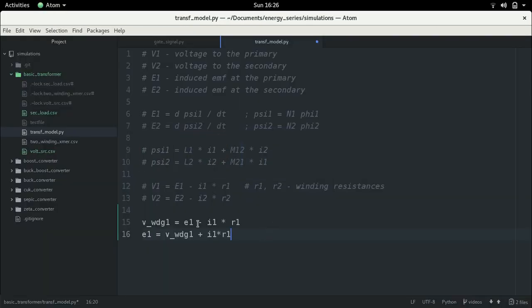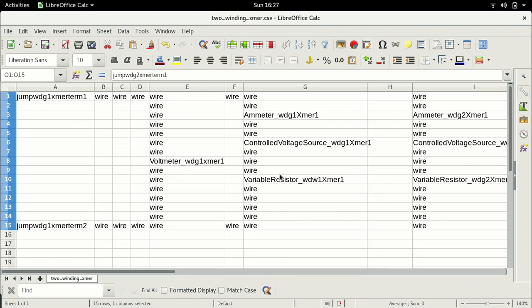So let us correct it here. This applied voltage is equal to this, let me copy this here, paste it, is equal to the induced EMF, right? So we don't have to do anything to calculate our induced EMF. Alright, this is just the KVL. I would say take a minute and think about the application. I am assuming always the current to be flowing into the winding, right? And if it is flowing into the winding and this induced EMF is such that the positive polarity is upwards, just do the KVL. This is what you get.